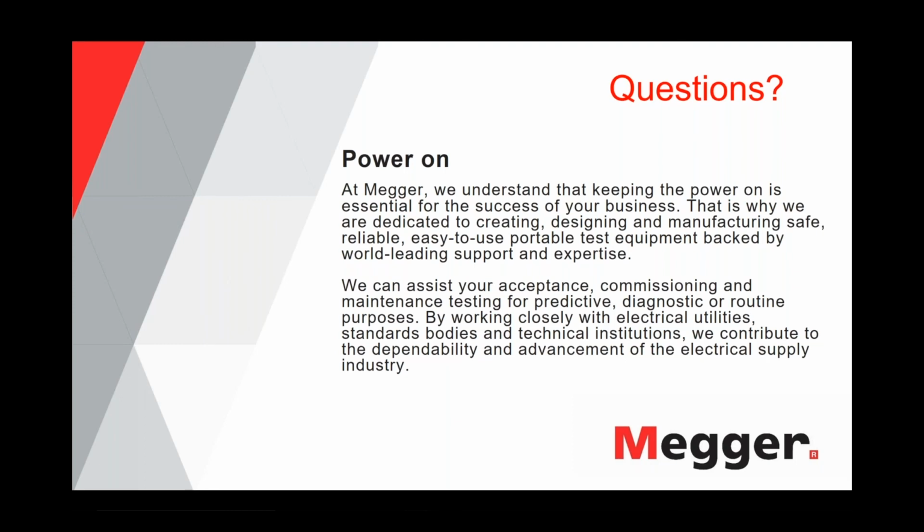So if you have, in an open substation, which is typically the case, terminations that are exposed to the environment, and you have isolated the termination, which you must, because you must test an isolated cable, then if you have rain, obviously you have moisture and you can get leakage over the termination, which will affect your reading.